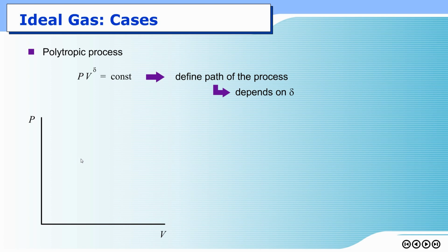Okay, that's one aspect of the PV diagram. The second thing when you see a PV chart is work, because work is normally obtained from the integration of PdV. Essentially, it is the area underneath the PV curve.